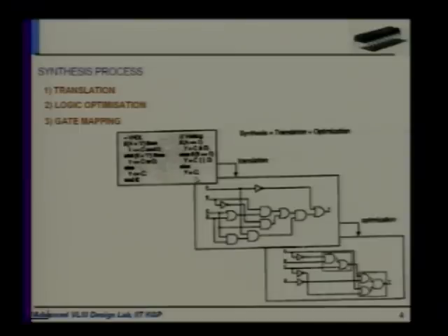Now, when we draw the logic design by hand, that is the simplest. You can see there, if you decode this, this will give this Verilog code. So this is the simplest translation process. Now this is done by the logic synthesizer. Logic synthesizer then optimizes the design. Why? To meet the constraints. Obviously there will be some constraints. If there are no constraints, it will not optimize it. Okay.